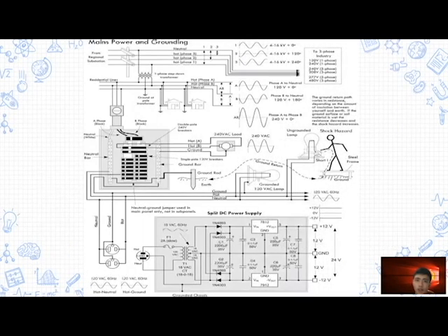Here is an example diagram of mains power and ground supplying in America. Let's look closely at the whole supply system. The three wires from the pole-mounted transformer are connected to a watt-hour meter, then enter a main circuit panel that is grounded to a long copper rod driven into the ground or to the steel in the home foundation.